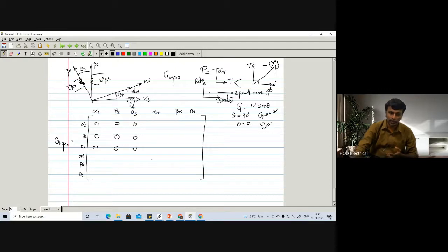Similarly, all the rotor variables, alpha, same axis, so we will not have any speed EMF. Therefore, alpha r, beta r, this will be 0. Then similarly, these three components, beta r and alpha r, are in the same rotor. So this is the rotor alone, and this is the stator alone, so we will not have any speed EMF, even though the angle between these two is 90 degrees, all are in only one component. There is no interaction between stator and rotor.